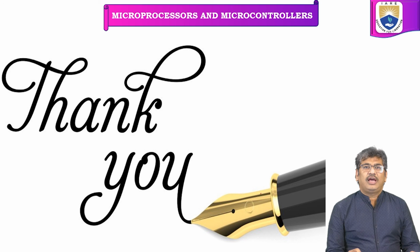The various steps we have to carry out for conversion are, first we have to select the input signal, which is through port B. So first we are going to select input 2 as per that program. If you want to select any other input, the port address lines we have to select on port B have to be changed. So 00H on port B is for input 0, 01H is for input 1, 02 is for input 2, 03 is for input 3, like this 07 is for input 7. So one of the inputs is selected by sending the proper value on port B.